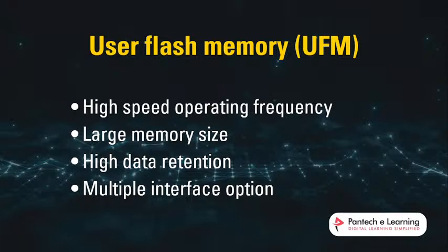Because our SRAM and DRAM are volatile in nature, the code we flash will be gone when the FPGA is off. So UFM is very much needed for RSU, remote system upgrade.